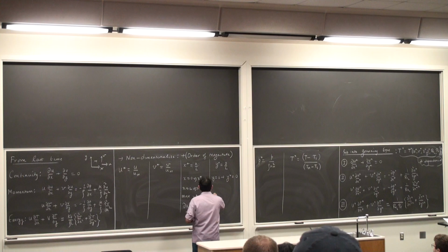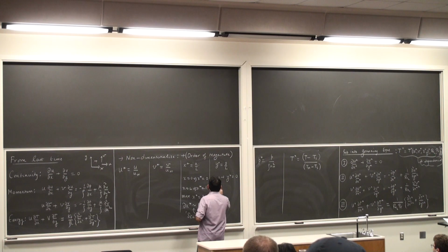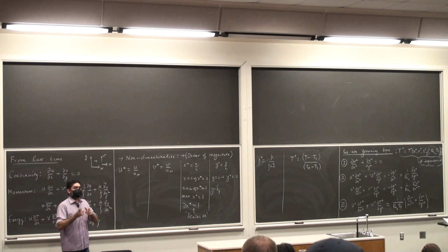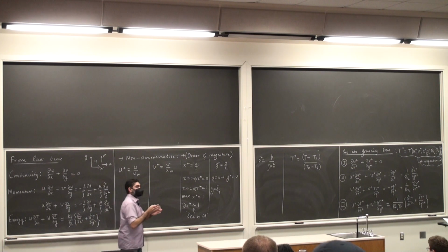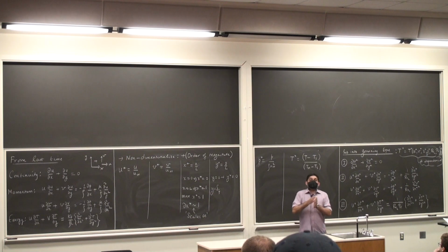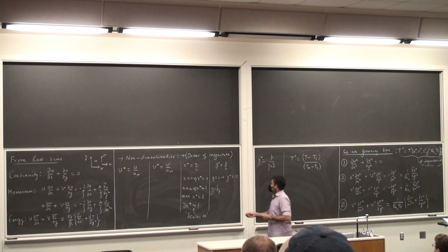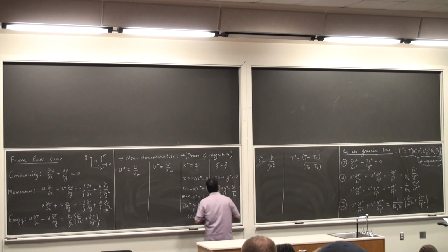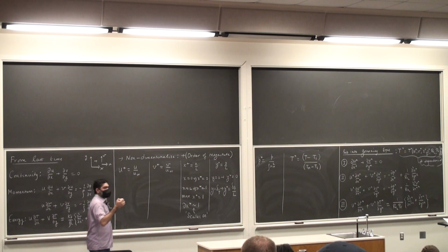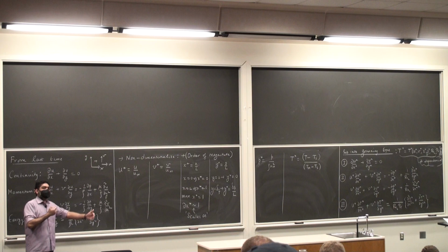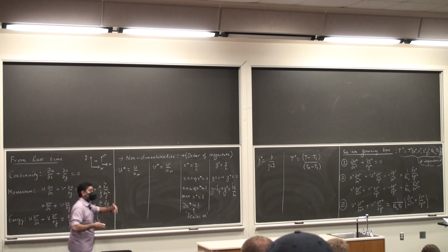See, when y is delta f, typically the fluid boundary layer thickness for us is more or less going to be thicker than the thermal boundary layer thickness. So I'm taking an order of magnitude approach here, taking the larger of the two, so that y star is delta f by L. Delta f is the boundary layer thickness, which is very small. L is the length of the plate, which is typically very large. So I'm going to call this ratio epsilon.